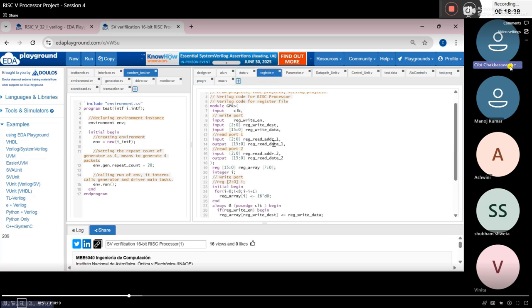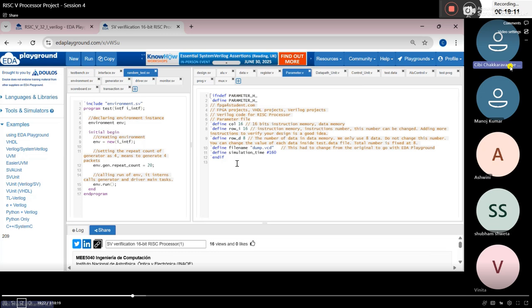And then there is a register. As I told you in the previous design, we use registers to load some data, and after loading that, using the registers, we are going to perform the arithmetic operations. For the loading purpose, where do we get the data? From the data memory. From the data memory we load some data, or we pass some data immediately, and perform the arithmetic operations.